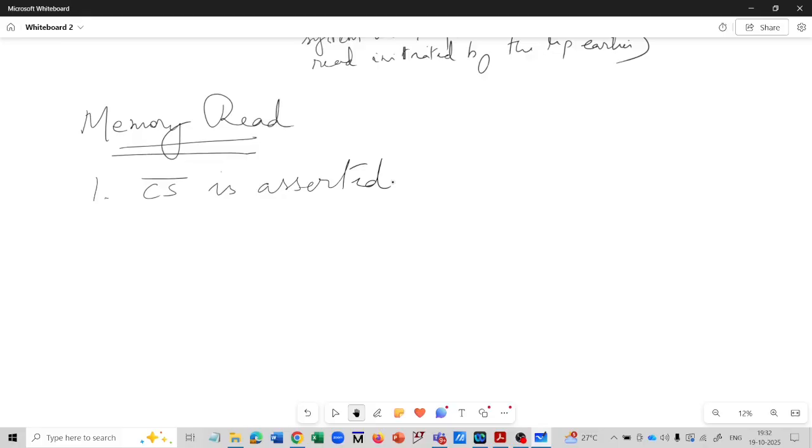That means the addresses corresponding to the status register or the data register, or the range of addresses that make up the memory map of the particular memory that is interfaced to this controller, is available in the address bus. So when this happens, the chip select is asserted.